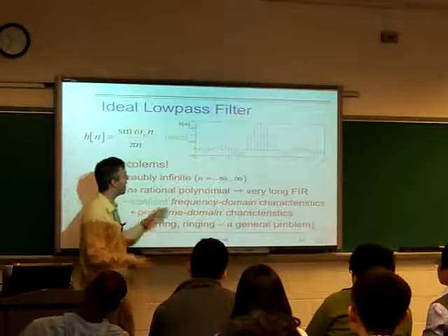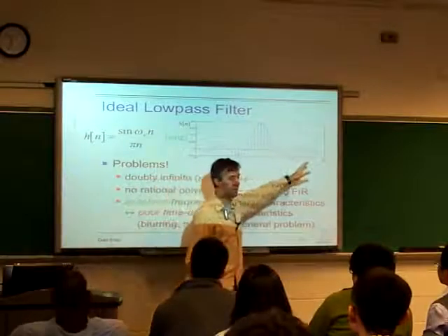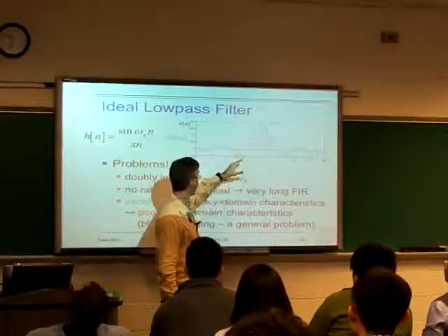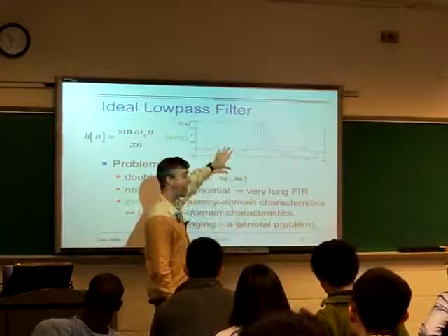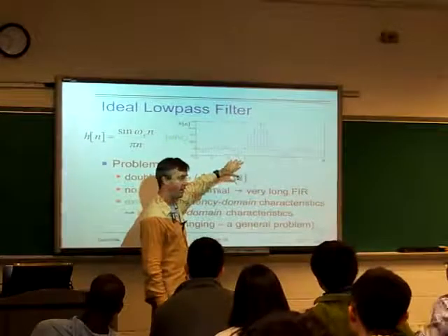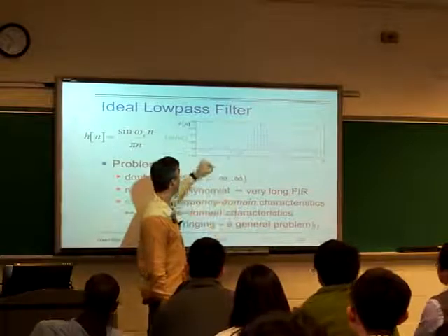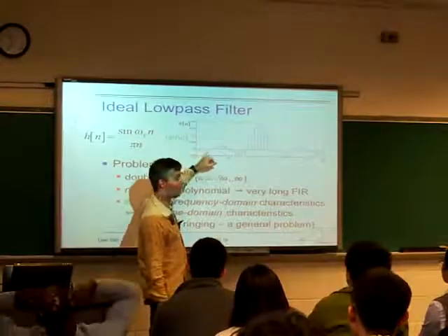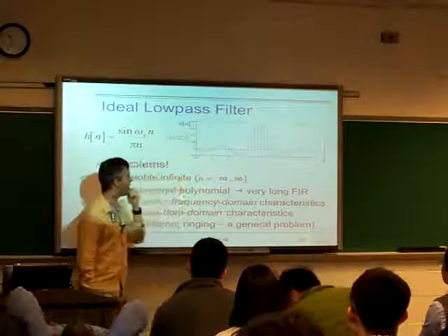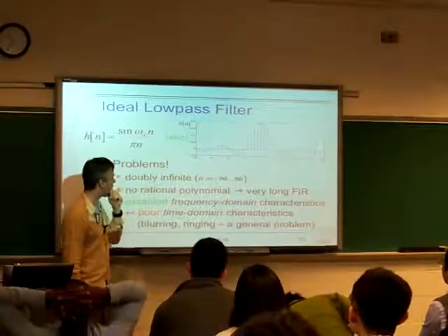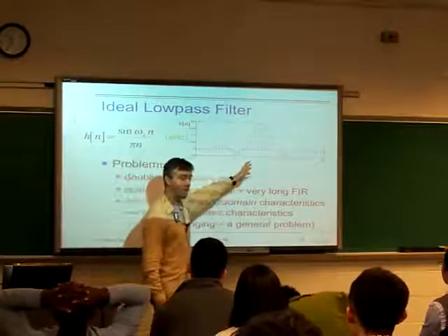So what we'd have then is a truncated version of sinc. I only plotted it from -20 to 20 points here. So this is the kind of thing we could actually do, where we just chop off the ends and forget about them, although the ends are not too small here. They'd still be visible even on this linear amplitude plot. But then this is what the impulse response would look like.